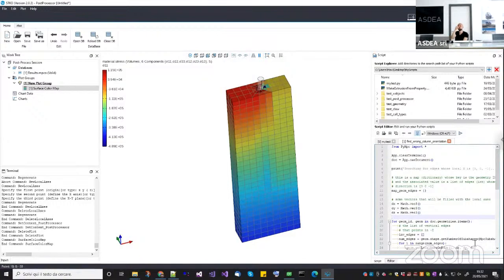So you can simply develop a script that takes the results from the MPCO output and creates a report text file for you. The problem is that if you want to use a standard OpenSees recorder with OpenSeesMP, it will be a mess, because you have to create the same recorder for each process, and if you want to record a stress on a certain element, you need to know what is the partition of that element. And that is not easy. So yes, I would suggest you use the MPCO recorder and the Python API.